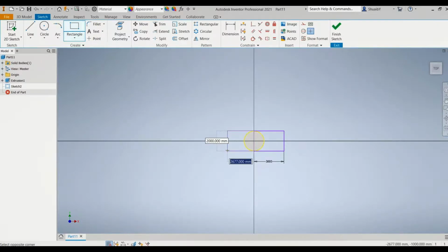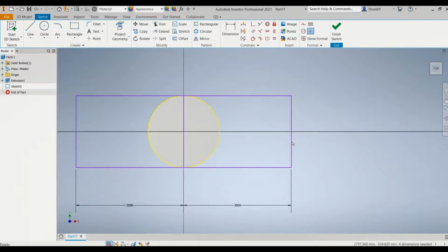And we're going to do the same thing on the left. So I will say pier cap left width equals 3 meters. It could also be 4 meters, whatever you want. It doesn't have to be even or symmetrical. And I have just done that. So again, pretty much AutoCAD.